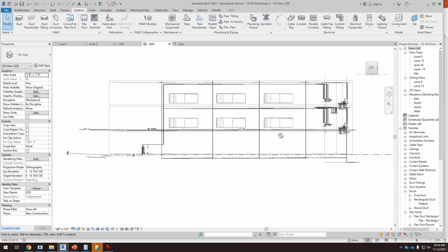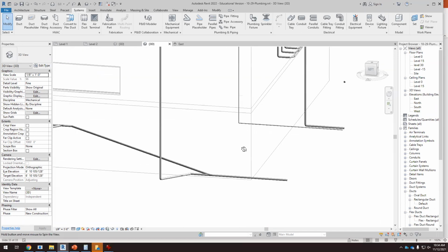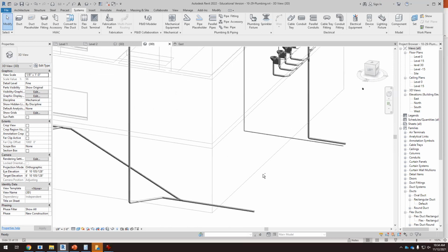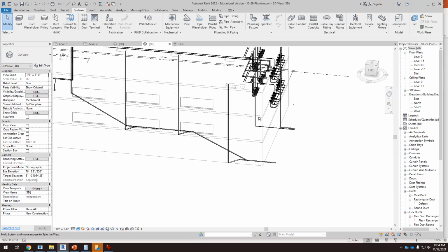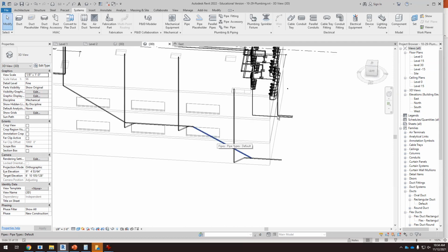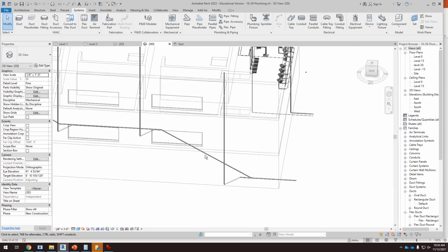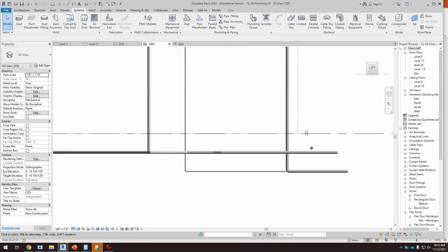And well, here you see that the height of this horizontal pipe that comes from the toilet, and this one that comes from the rain, is different. It makes sense. This building is not complicated, it's very simple, but sometimes we have to lay out the horizontal pipe from the toilet and the horizontal pipe from the rain, and they intersect each other. So that's why working with 2 different levels might work, so that we don't have this intersection.